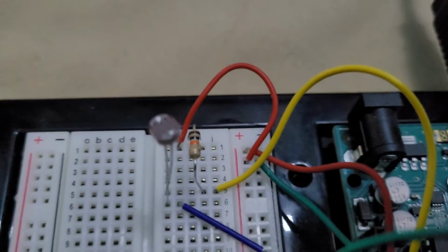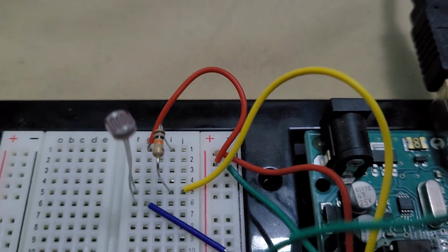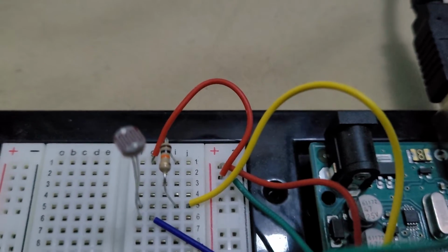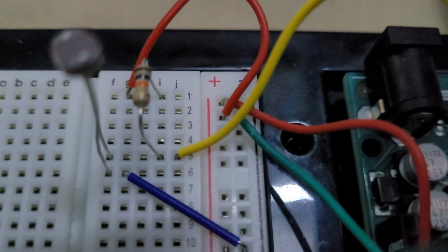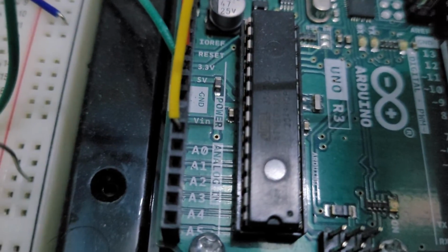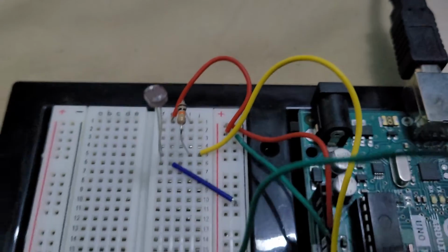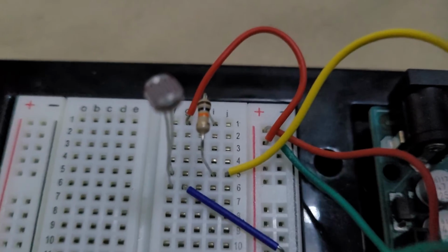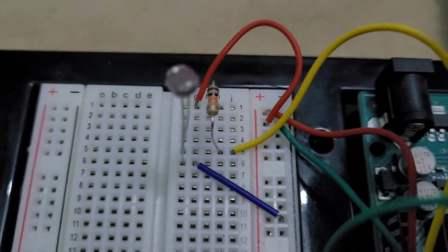We do have our photoresistor hooked up to a 10k ohm resistor, and the 10k ohm resistor is going to be connected to the positive terminal for the 5-volt, and as well to row 5 right there. The yellow wire, row 5, is going to be connected over here to analog 0, and that's where it'll be getting the readings of the light, so that it can know what to map out for the LED. And the negative, the cathode, is connected over here to the negative terminal with the blue wire. And that's it for our photoresistor.